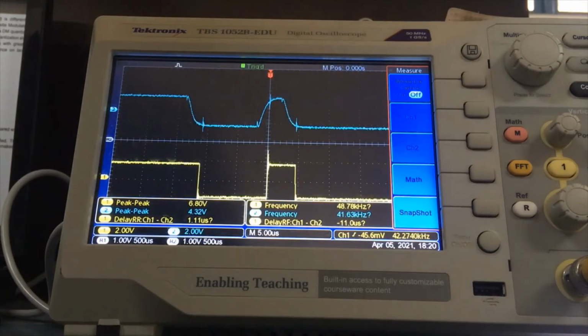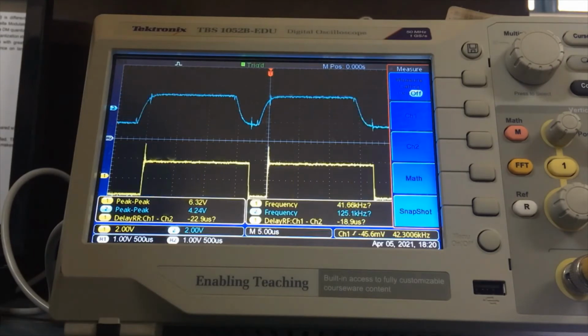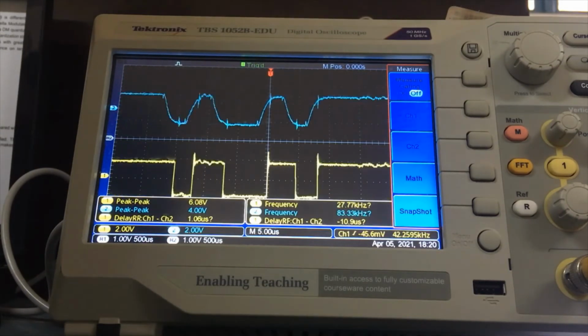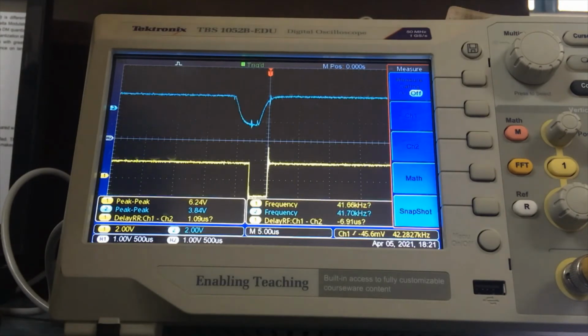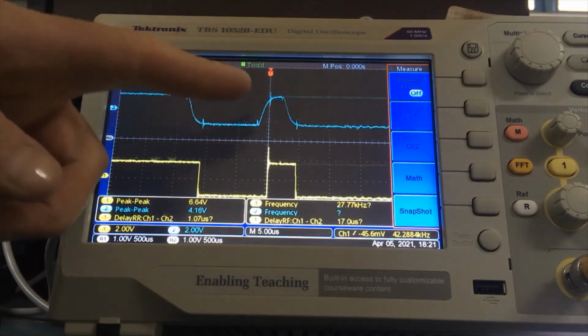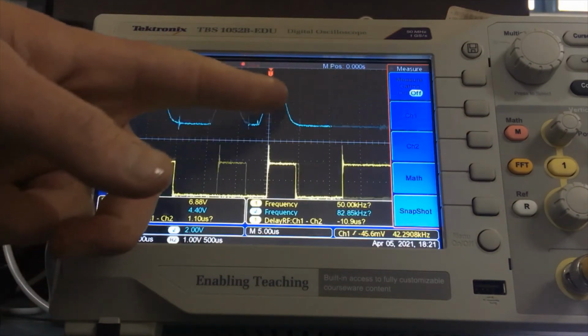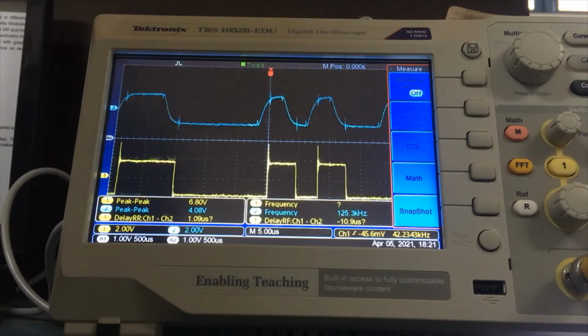Okay, now in order to see the functioning of the clock and data recovery stage, above is the output of the channel, which is acting as a low pass filter, right? And the higher frequencies, as you can see, it has been exaggerated, so the higher frequencies are missing. The sampling frequency I have taken is 32 kilohertz, capped to the maximum.